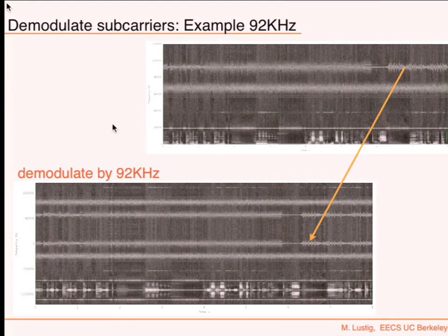After demodulation, what I did here is a complex demodulation. Complex demodulation basically circularly shifts the spectrum. The spectrum that was up here is now down here, so everything shifts down. Now I'm showing the full complex two-sided spectrum. Now it's centered around this 96 kilohertz, everything is moved down, and then you see the circular shift of it.